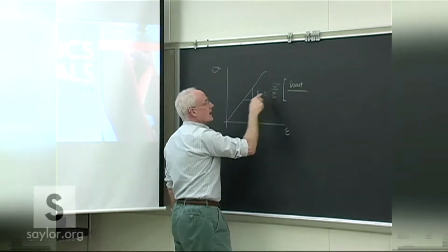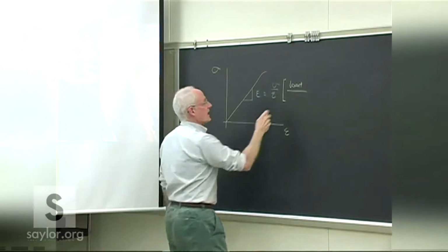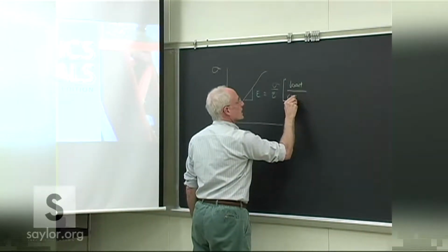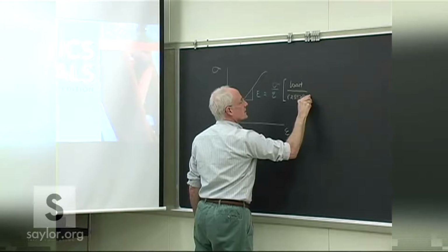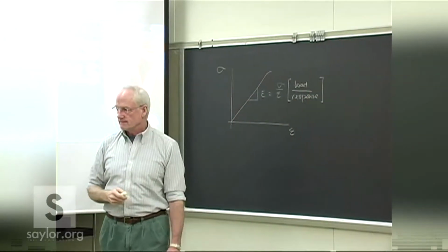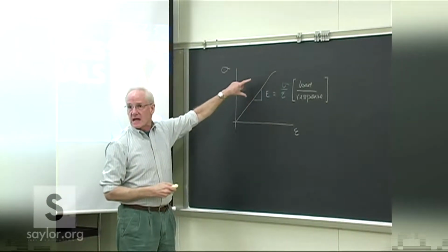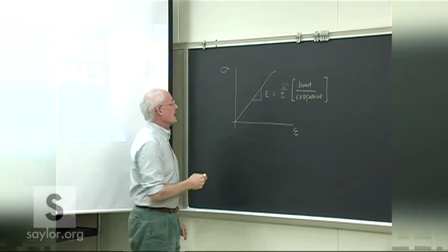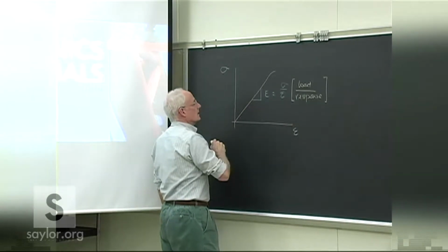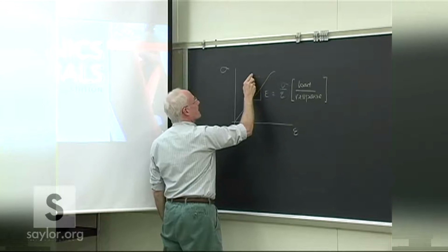And then the strain is an actual deformation due to that load. So this is kind of like a ratio of load to response for a material. And this is the major design region in which we stay because of its predictability, linearity, and the like.